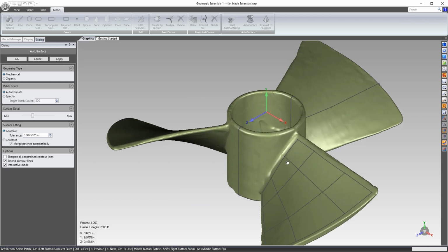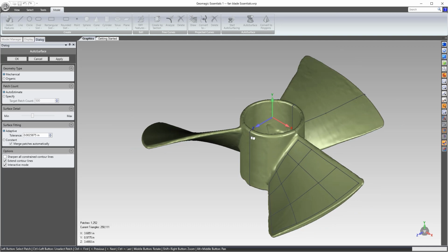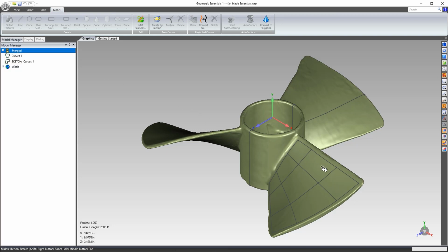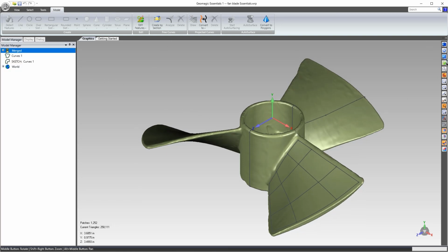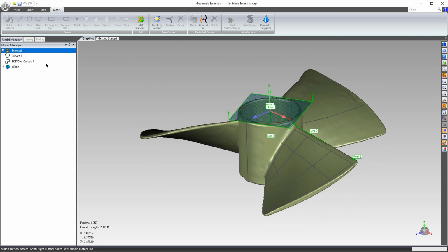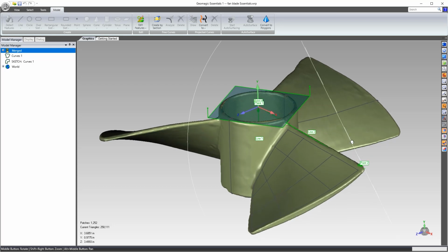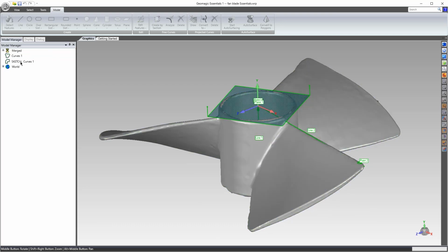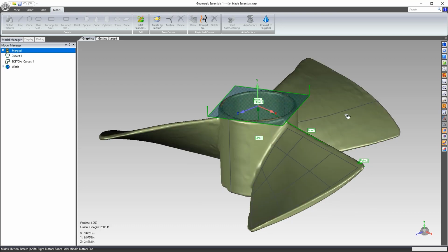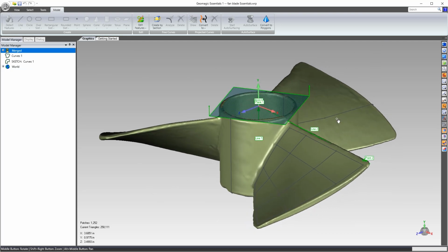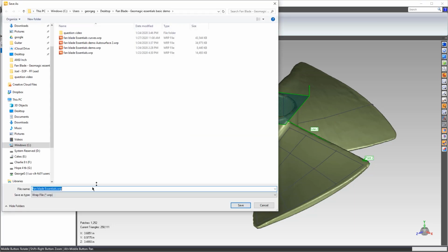So now the auto surface is finished. So you can see the curves, the CAD solid, well, it's a surface, not a solid, and the features. So I can write all of these to an IGES file and send them over to Solid Edge. So if I grab all of these, I can save them out to an IGES. So that's the next step, is to go ahead and save these over to Solid Edge. So if I just come over to Save As, IGES, and I will just name my file.